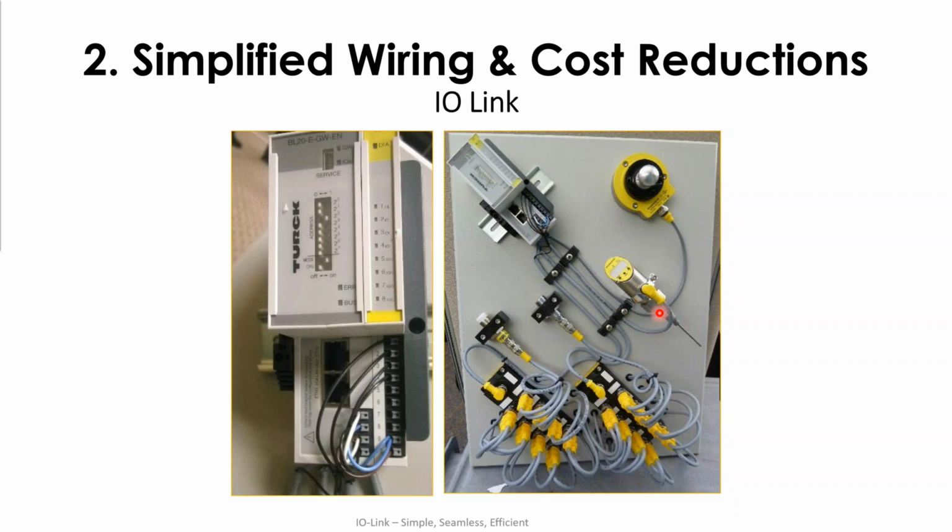This temperature transmitter, we now have an IO-Link version of that. And then instead of these multi-port bricks with the multi-pin home run connector, we now have a multi-port brick like this one that just takes that 3-wire unshielded cable back to the IO-Link master. And so we've saved with our multi-pin cable, which is a little more expensive and they can be difficult to run, gone down to the 3-pin unshielded cable.